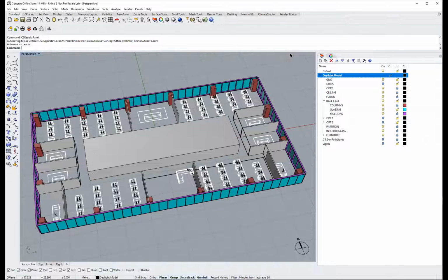Well, for daylight, there are really two big categories of question that we want to ask. The first is, is there sufficient daylight? Meaning, does enough light pass through the facade and onto the work plane that people can do work tasks without the aid of electric lighting? And if so, that really has two benefits. One, we replace the need for electric lighting, which cuts our energy bills. But secondly, we also are guaranteeing a sufficient supply of broad spectrum, blue enriched light that's going to keep our occupants healthier and more productive.